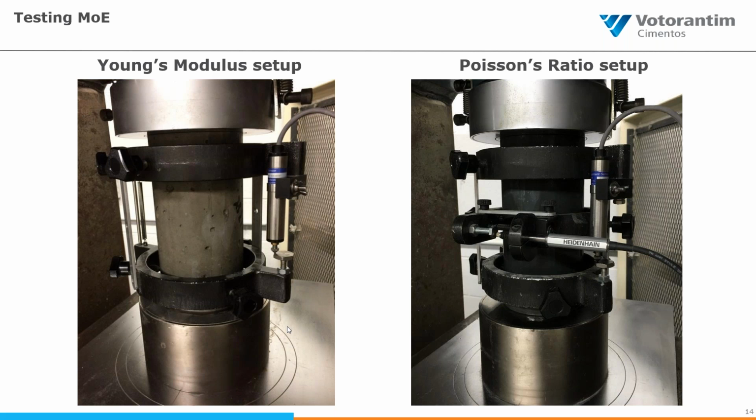It's very important because when all this testing started in 2016, very few local testing labs were actually set up to have machines that had a controlled unload feature when they were running this test. And we found that that tends to add a lot of abuse to the cylinder, which ultimately gets you very diminishing returns as you go from the first to the second to the third peak run of the ASTM spec. So should you be working with a testing lab, make sure that they actually have a true Modulus setup so they can run it completely under controlled unload and load.